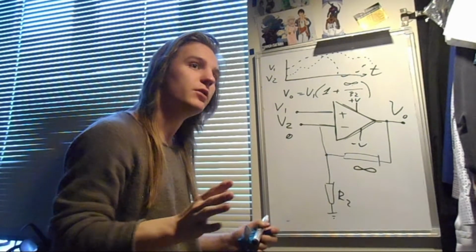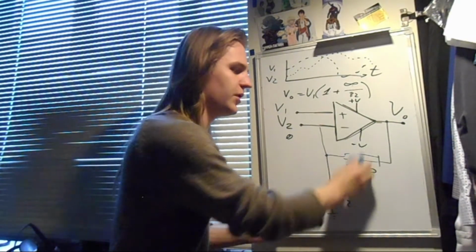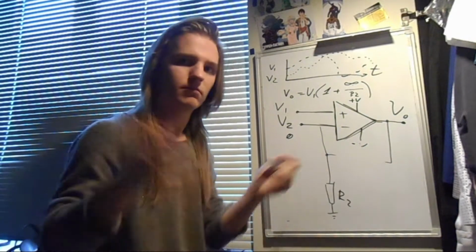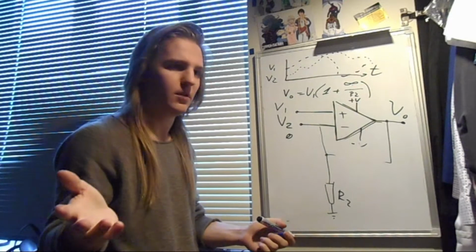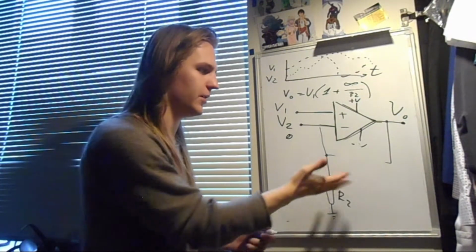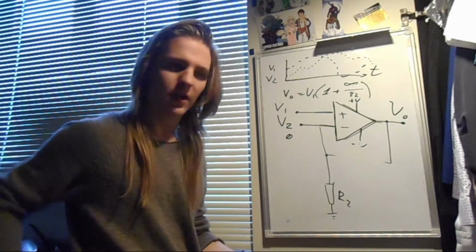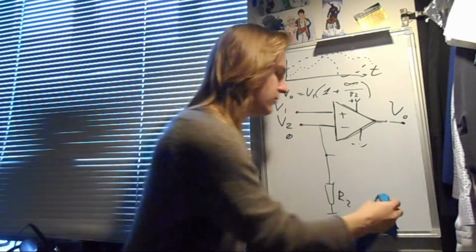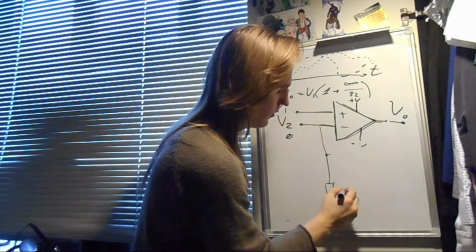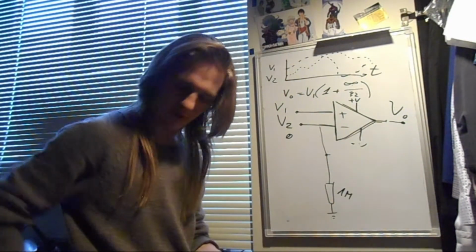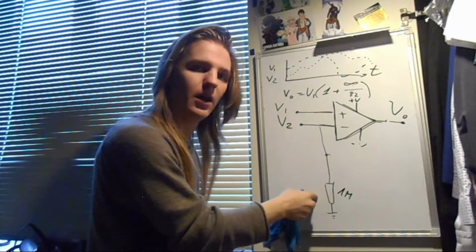Last question is, how do you get infinite resistance? Well, very simple. You just erase it. If there is nothing in here, it's like infinite resistance. Resistance blocks current from flowing, and if you have no wire, then current simply doesn't flow, right? Okay. Now we will make this R2 equal to 1 mega ohm. So if we do not apply any voltage here, it would go to ground.